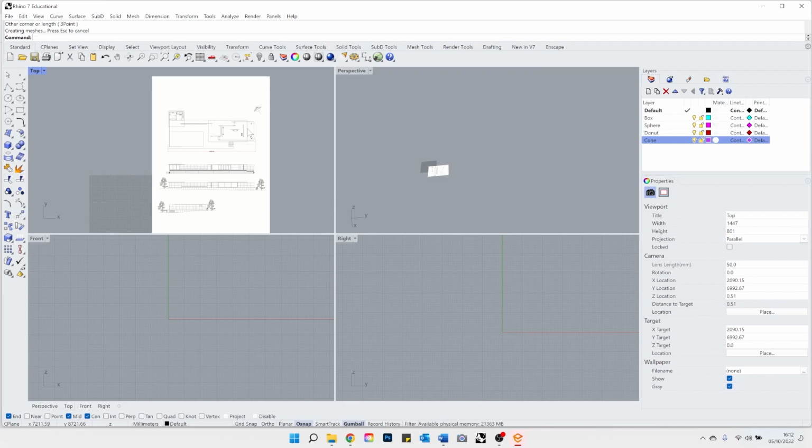If you're lucky enough, and if you have your technical drawings given to you as PDF, sometimes those PDFs are saved as vectorized PDF. That means that all the data, all the technical drawings, all the floor plans and elevations actually preserved their vector data. So when you bring the PDF into Rhino, it opens up and straight away it's a fully drawn floor plan. So you don't need to trace it over. It saves you like a week of work.